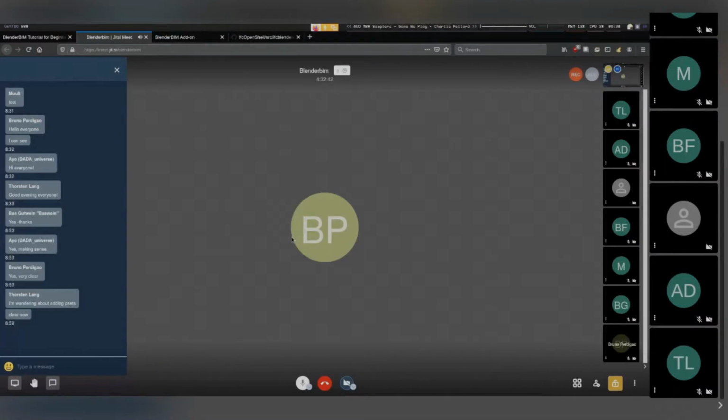All the documentation features are in the Output Properties tab here. Just like any other BIM program, you can create views, sheets, and put views on sheets, and you can cut sections. A view is any model cut. It can be a section, a plan, an RCP. It doesn't really matter. Now, the interface for this is absolutely horrible, and it will be fixed.